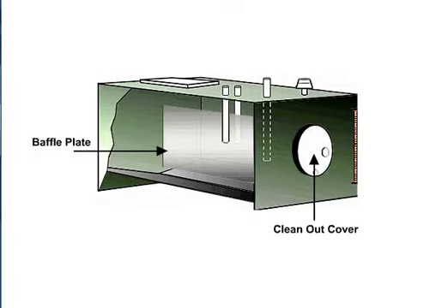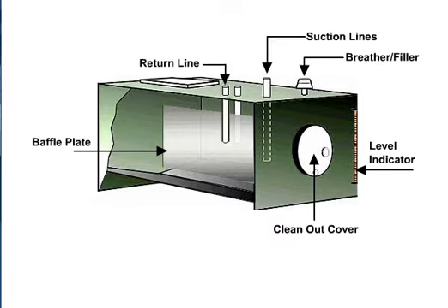a cleanout cover for maintenance access, a filter breather assembly to allow air exchange, a filler opening well protected from contaminant ingression, a level indicator allowing upper and lower levels of fluid to be monitored, and adequate connections and fittings for suction lines, return lines, and drain lines.